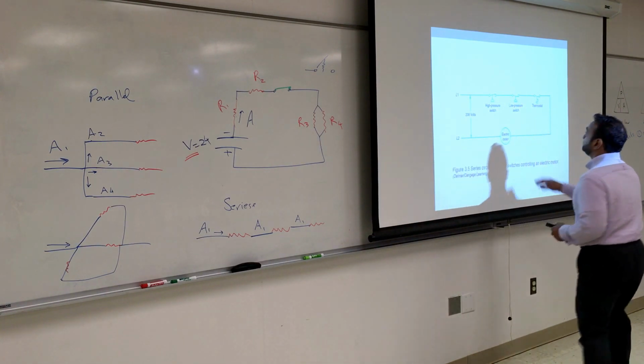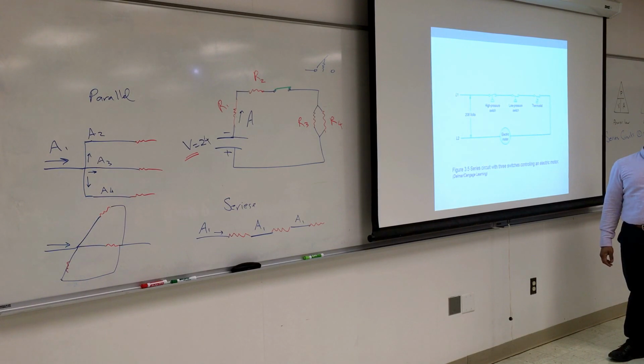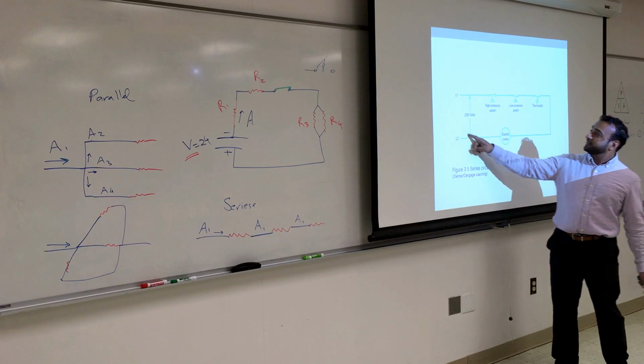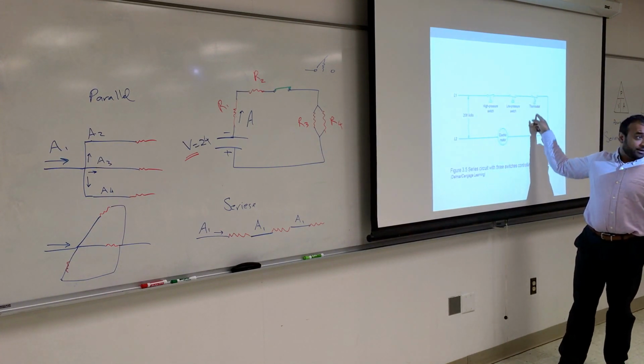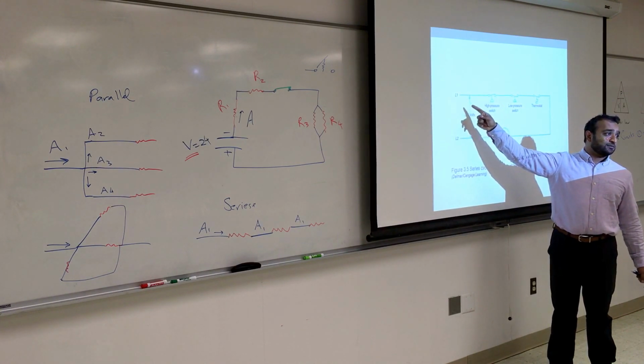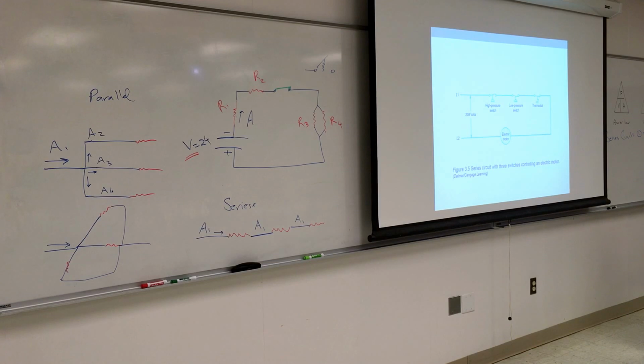That's an example for 3 switches in series or parallel. What's in parallel? I was looking at 208, I thought that was. I know, it's confusing, but always follow the current. Yeah. So line 1, which usually line 1 is hot, so they will say line 1, or they will say hot or black. Those 3 switches are in series.